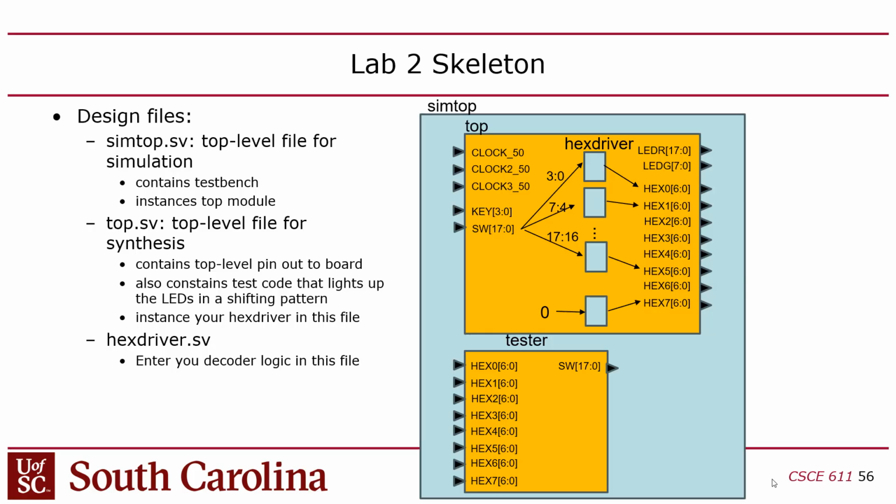It's called, I think, labhex.qsf. I don't know what QSF stands for, but it's a Tcl script that you run when you open the project, right? And that project file is what contains your pin mappings that map the magic names to the actual Excel spreadsheet pin things, right, for the FPGA. That's all in the project file, so that's all done for you.